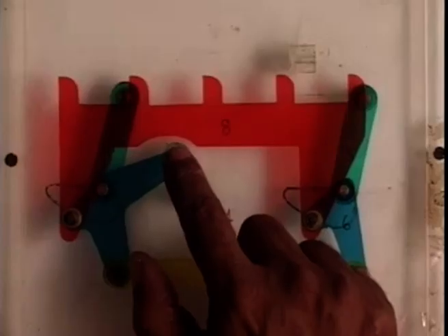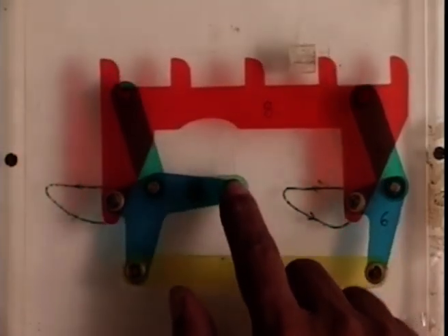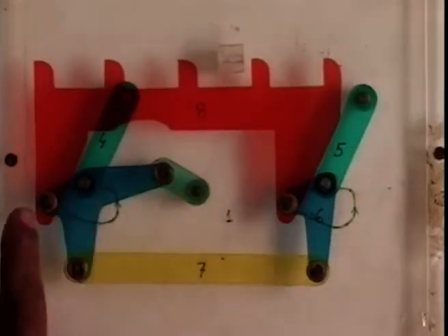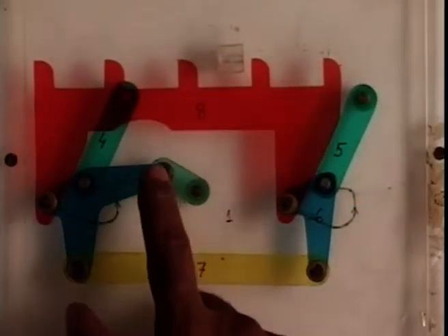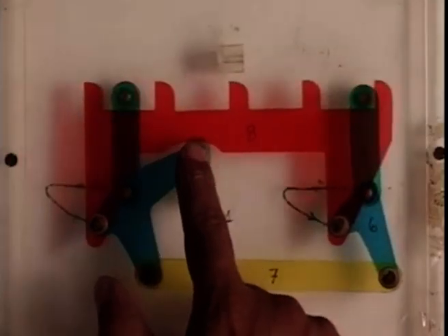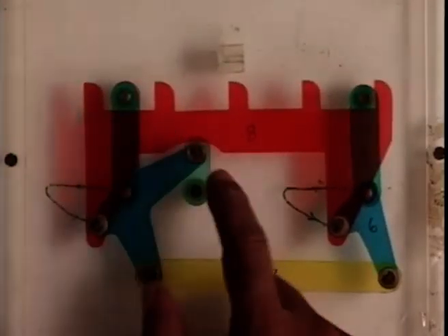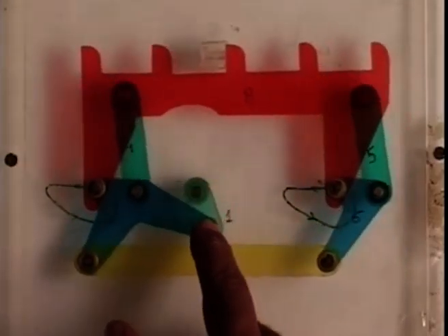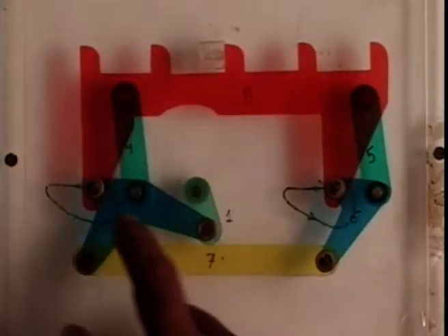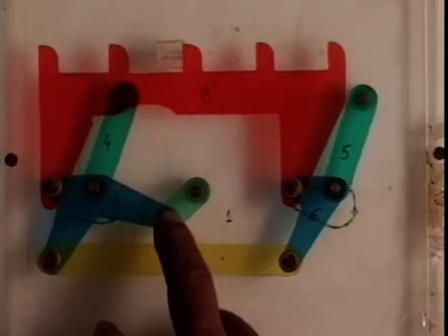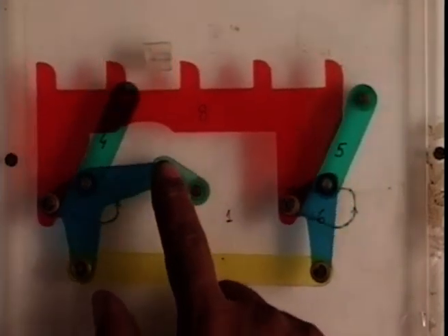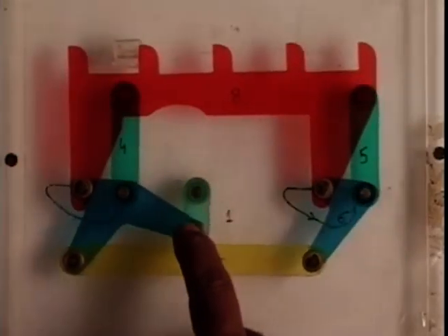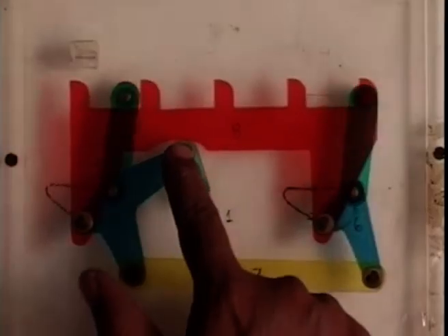It has left the object, it is now being picked up and pushed. Again it is left because this coupler point is coming down. Now this coupler point, due to this vertical path, is going up and again picking up the object, and now because of this horizontal path, it is pushed horizontally to the next station. Again it is picked up and pushed to the next station and left.